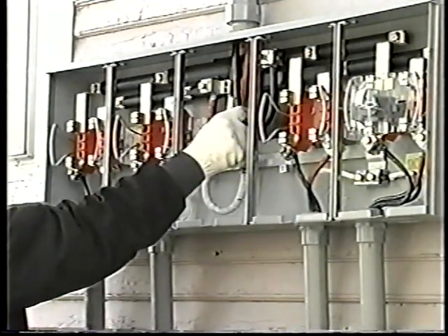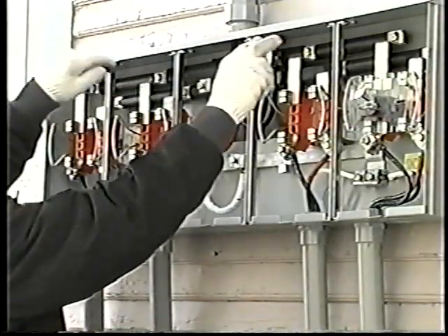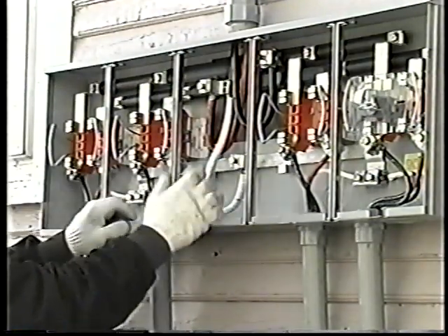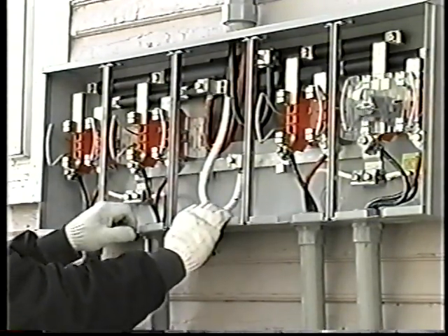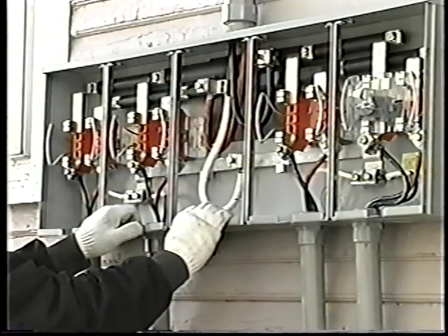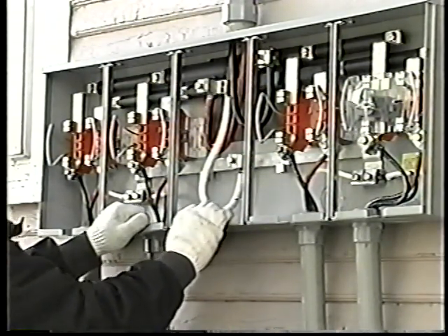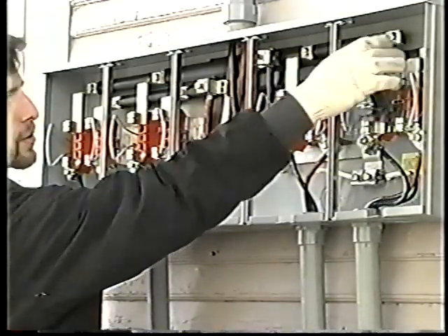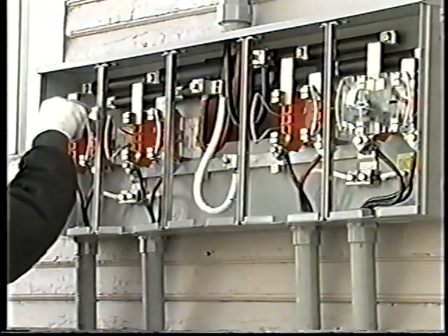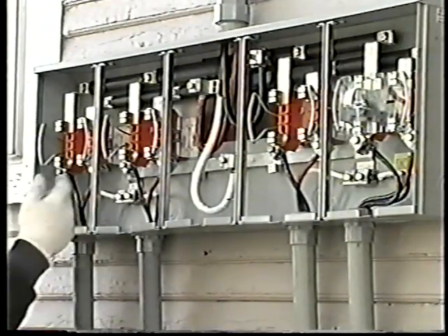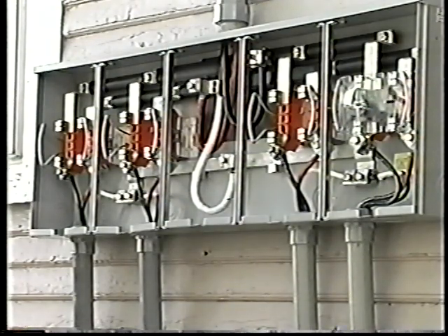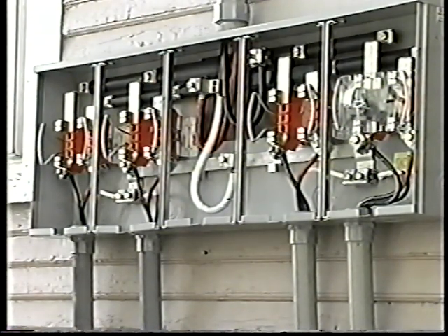We've got one of our hot wires coming in, goes across this upper bar, and when they produce this equipment, they install it already for us, so we don't have to connect anything between the top of the meter and those bars. They've got jumpers already bolted in all the spaces where there's going to be meter sockets. And this is pretty much the basic design of every meter bank that you're going to buy.